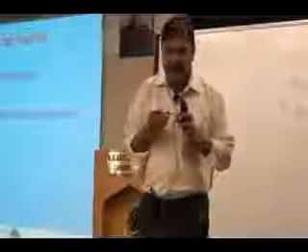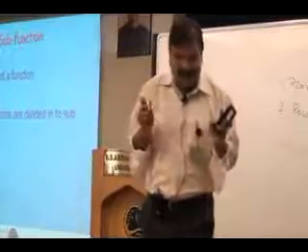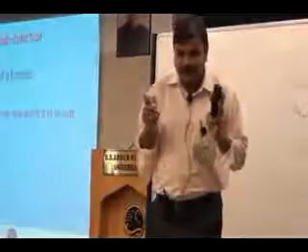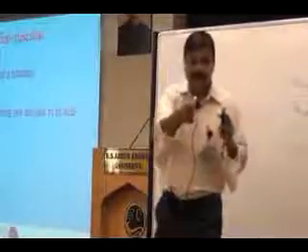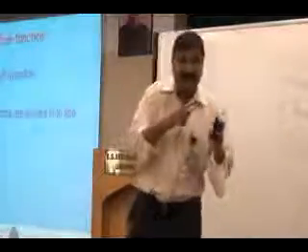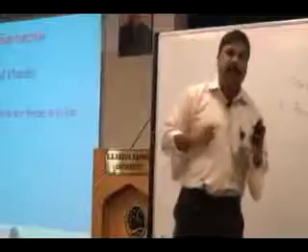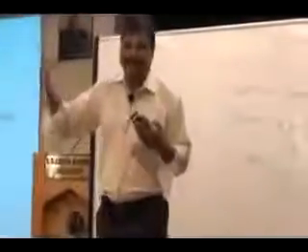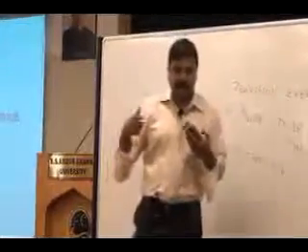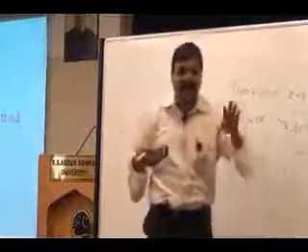Does a gear control power? Control speed. Is the power increased or decreased? What is increased or decreased in a gear? Speed. Yes. It is the speed which is increased or decreased, or to be more precise, it is equally true to call it a torque. It is increased or decreased. Power almost remains constant.